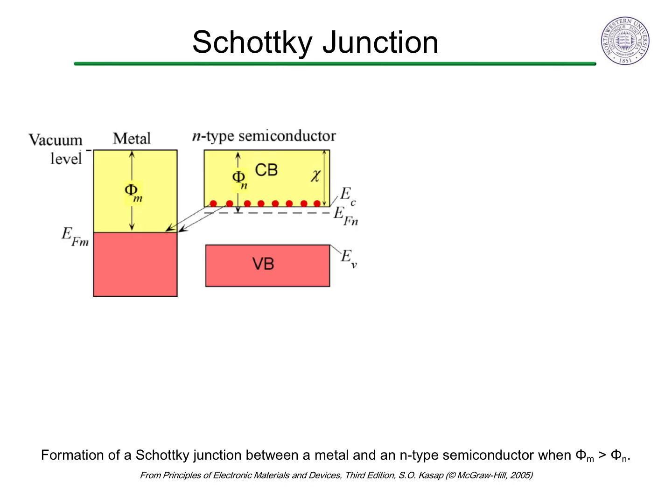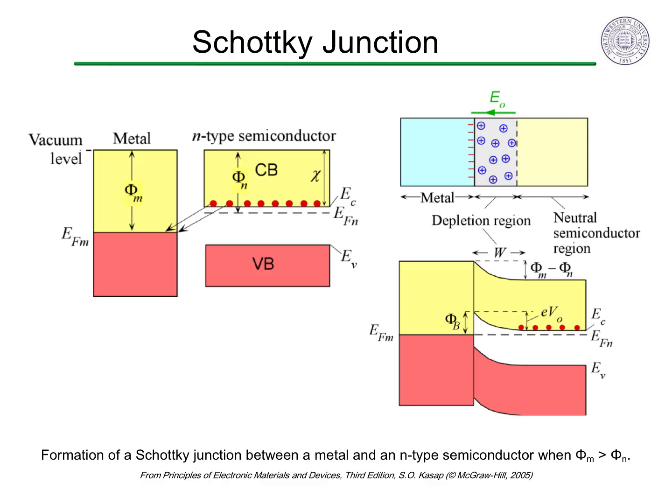Imagine we are trying to make a metal semiconductor junction. Now we have two different materials, one with a band gap and one without. Again, electrons will move from the material with higher Fermi level to the one with lower Fermi level, in this case from the semiconductor to the metal. Like the p-n junction, this will lead to a depletion region, internal electric field, and band bending. The bands will bend to make the Fermi level constant throughout. This means that the electric potential will be produced that raises the left side and lowers the right side.